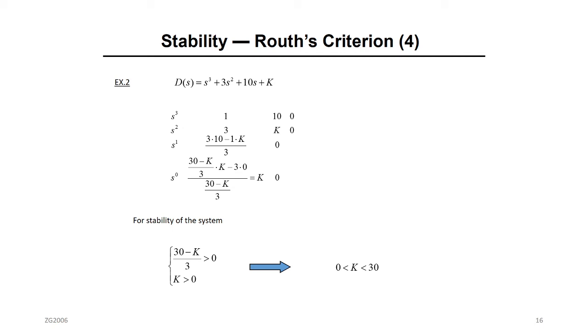All right. This is the last example for this chapter, and this is the first example for you guys to start designing the controller. We want to design the controller for stability. So you see here, we have a controller here. How do I know there is a controller? There is K here. This is the proportional controller.